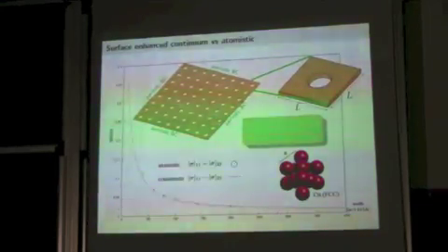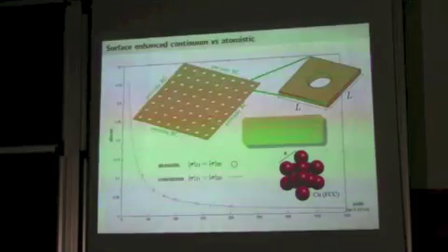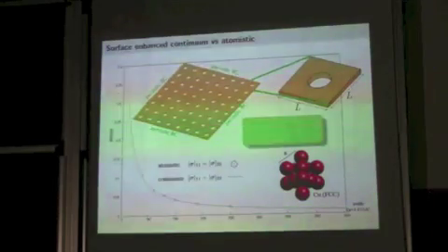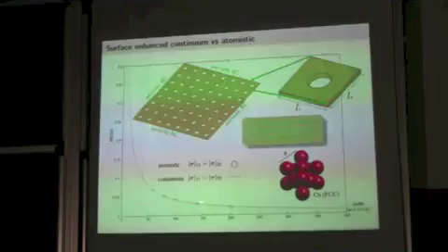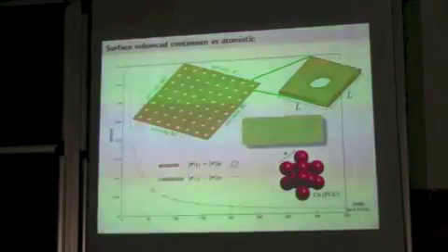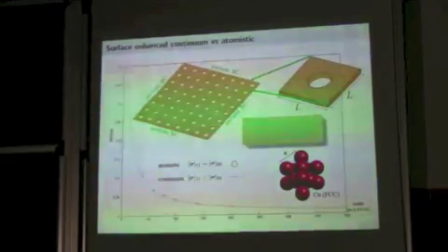So what we do is that we just, from atomistic calculation, you basically remove this hole, then you let it relax. Due to this relaxation, you introduce some stress to your material. And then from those stresses induced in the material, you can calculate your surface material parameters, if you like. So again, I repeat, this is not a curve fitting. So what we did is basically to look only at this size, so 140. For the size 140, we do all the calculations, we get the material parameters and everything. Then exactly with those parameters, I calculate this curve from continuum mechanics approach.